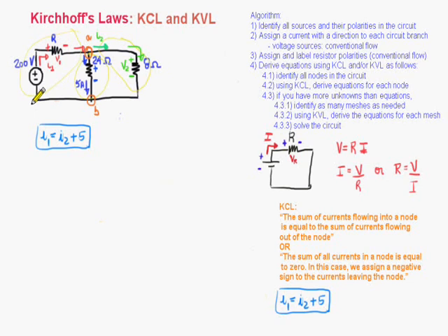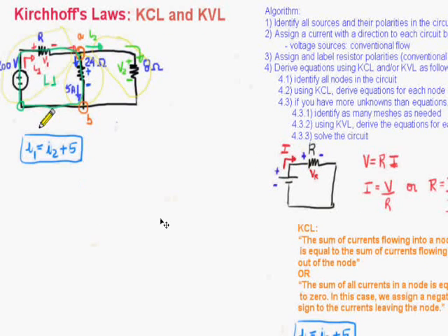Let's start by picking a point. I'm gonna pick this point right here, and I'm gonna use clockwise direction, and let's trace a loop here. I'm gonna pass through the voltage source, the resistor R, the 24, and I'm closing my loop right here. And since there's no branch inside, it's also a mesh. But I have a closed circuit path here. I'm gonna call this my L1.